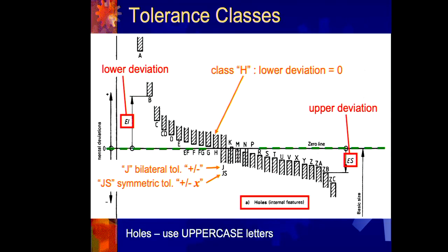And there's a bit more detail. I've focused there the H for you. EI means the lower deviation. ES corresponds to the upper deviation. It swaps as we go on either side of the H value. We get that swapping effect. I will not ever really ask you subtle questions about this J and JS stuff. It'll always be, give me a deviation diagram for a fit. And there'll be two rectangles that you'll have to produce, and then you'll be able to talk about how those rectangles come together, hole and shaft, to create a fit, and what kind of fit it will be.